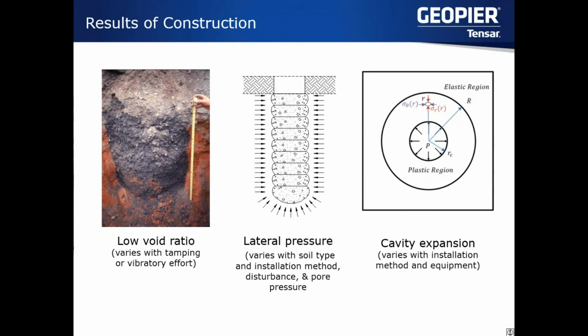For rigid inclusions, normally we're using a displacement system. That would involve driving our mandrel to whatever installation depth we're supporting. So oftentimes there isn't a need to pre-drill. It's just strict displacement, and the mandrel will just be driven to whatever depth we're trying to go.